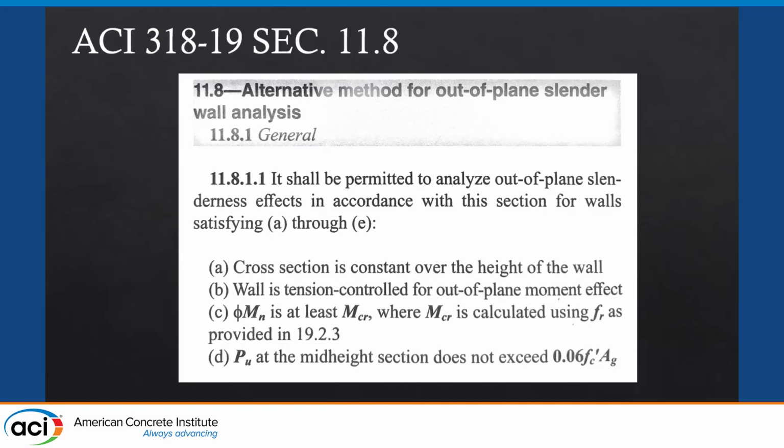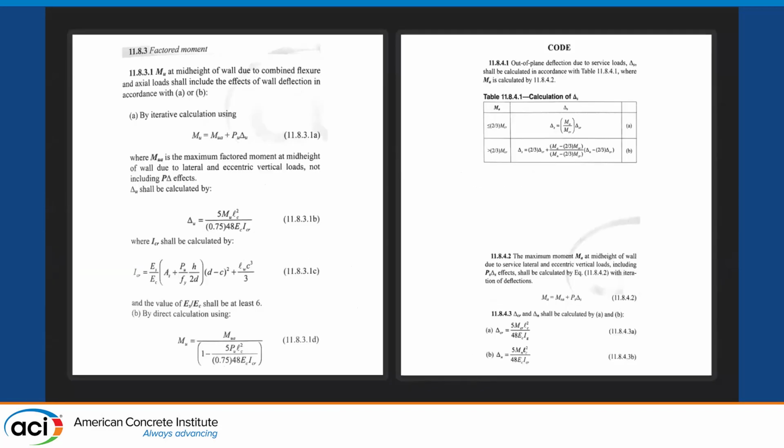Something to note about ACI is that the modulus of rupture of concrete, fr, you can see there, is used in ACI as 7.5, whereas the original testing used 5. So to account for this, ACI incorporated the 2/3 factor when you're applying to cracked.